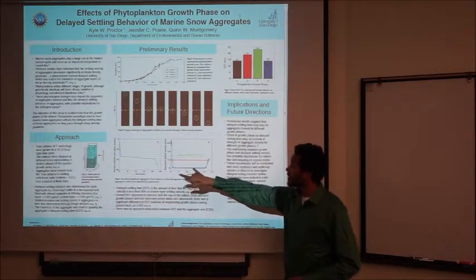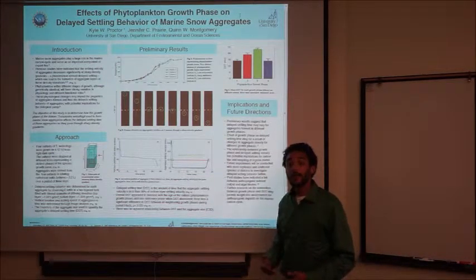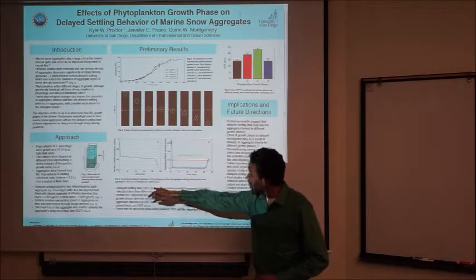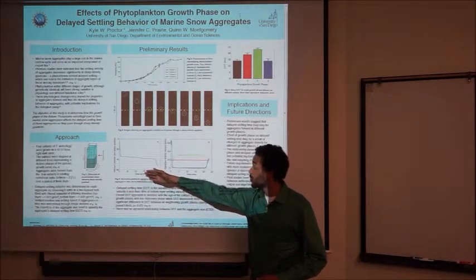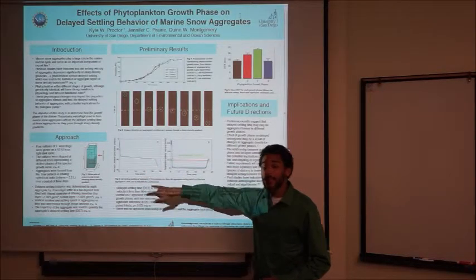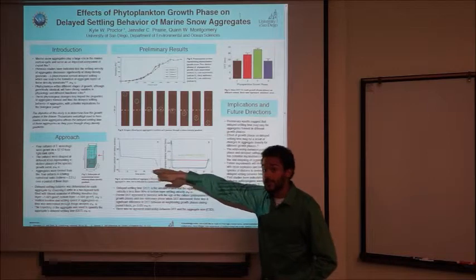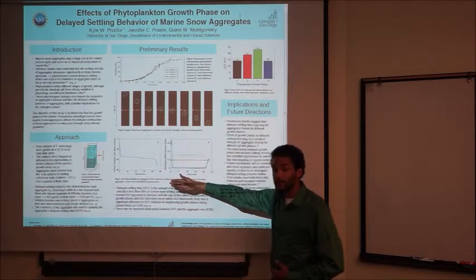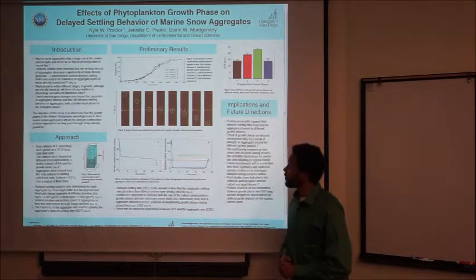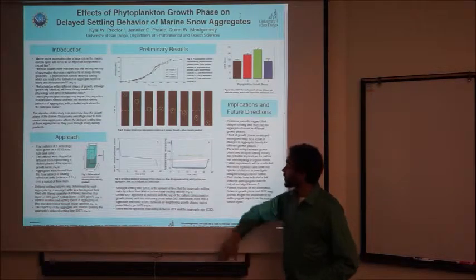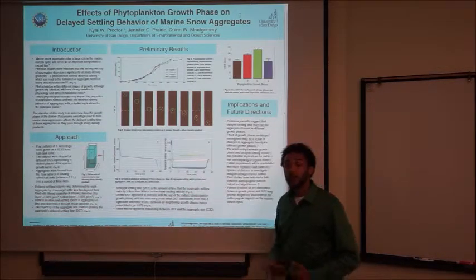Here in figure 4, you can see 2 figures that come from our MATLAB analysis of this data. Figure A represents a position graph. We have the vertical location on the y-axis, and this roughly parallels what we see in figure 3. It drops sharply, stays at the density transition, and then continues dropping. In figure B, we have the velocity of the aggregate graphed on the y-axis. Using this information, we were able to find the delayed settling time, or DST, for each aggregate.